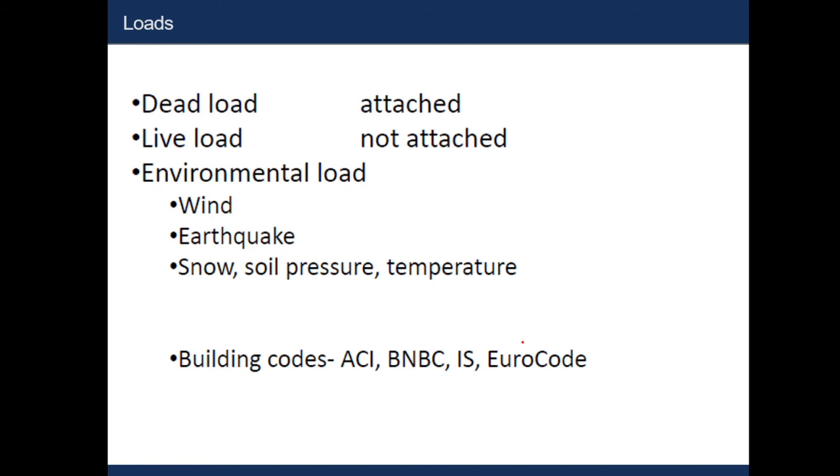Now let's come to the types of loads, starting with the dead load, live load, and environmental load. So what is dead load? Dead load is actually the self weight, and it is attached with the structure. Live loads are not attached with the structure; they are movable loads. And the third one is environmental load. In environmental load, we have wind load, earthquake load, loads due to snow, soil pressure, and